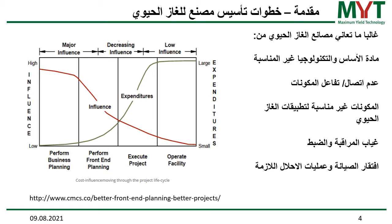So once you have built in a non-fitting component, then you will face a lot of wear and tear. You will face a lot of standstill of the biogas facility because stones will block your pump, stones will make your maceration system dull, things like that. That's why you must make sure that your substrate really fits the technology.